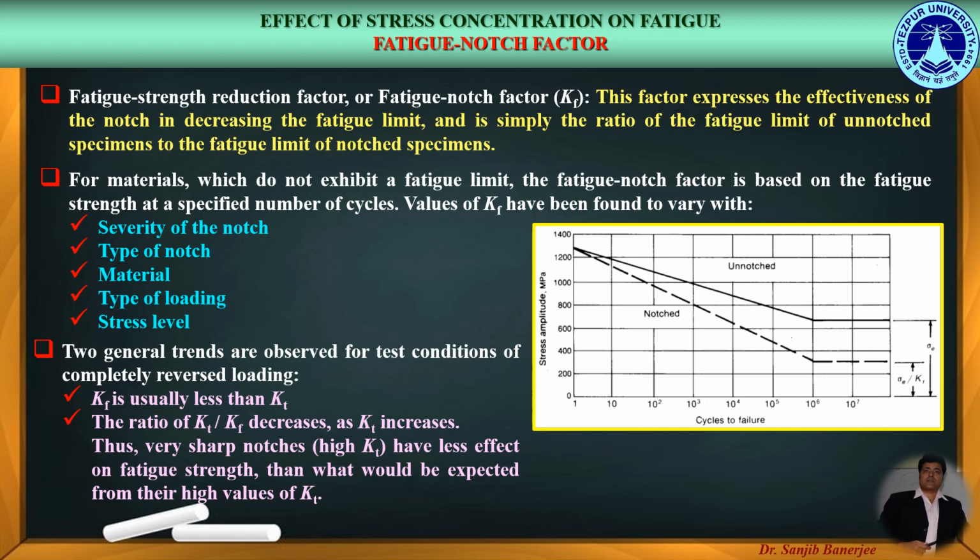Now the values of Kf have been found to vary with several parameters like the severity of the notch, the type of the notch, material, type of loading and stress level.